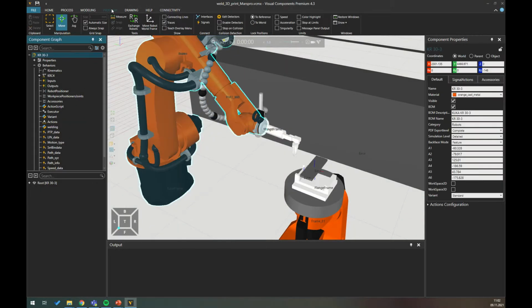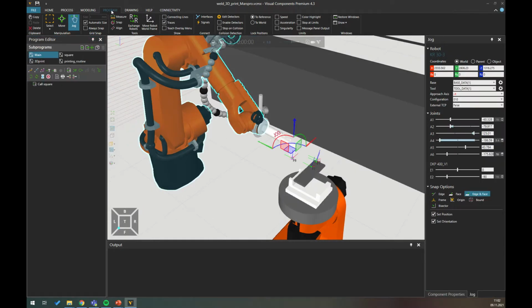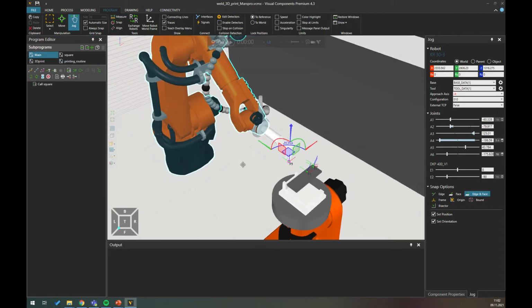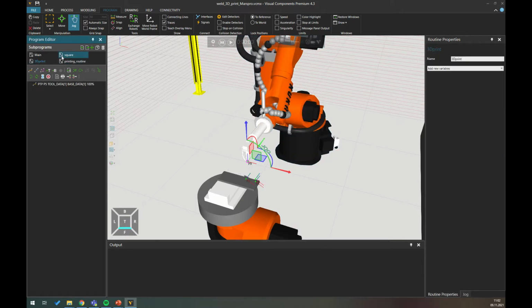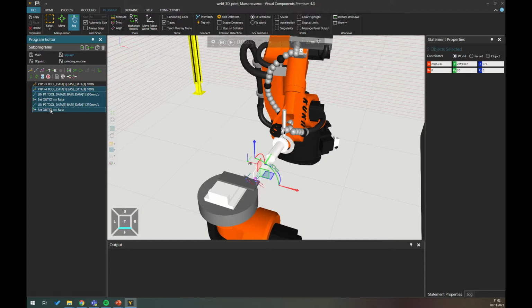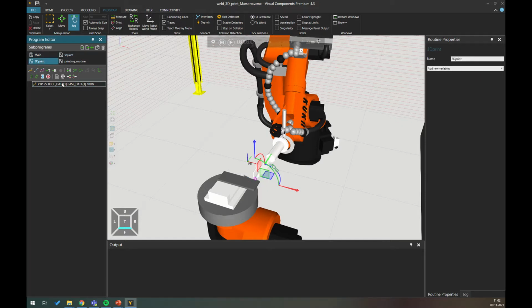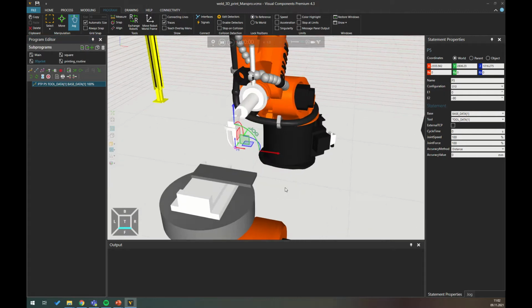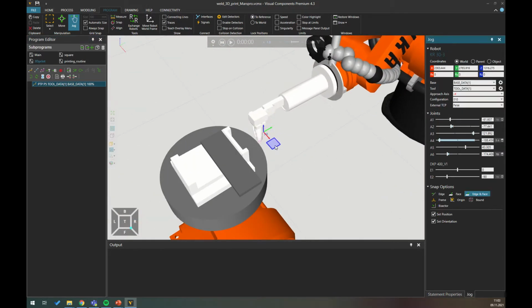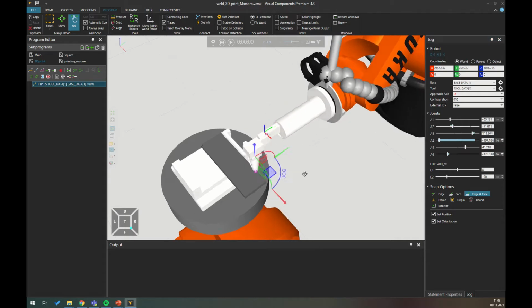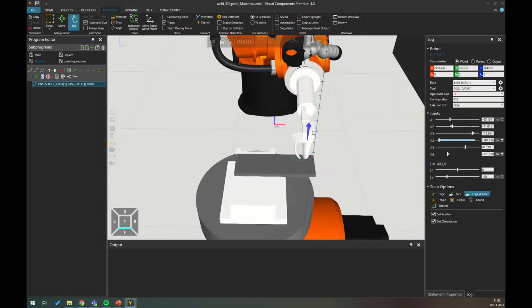After 3D printing has been enabled, you can then move over to Program, which is then again used for programming of the system, similar to the last module, Simulation Welding. As you can see, there are a few sub-programs in the tab. In this case, for doing the 3D printing, we're using the 3D Print sub-program. This is the place you add the position and create the program. For the first part, we're going to weld a straight line.